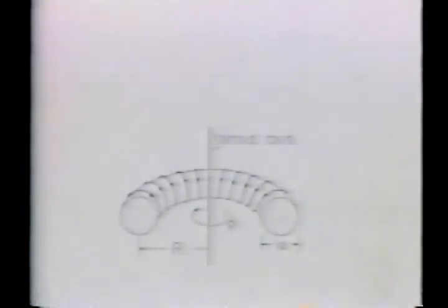A toroidal coil is tightly wound onto a donut-shaped magnetizable core. Each turn carries a current I. For the toroidal geometry, Ampere's integral law is enough to relate the current I to the H field in the magnetizable core material. Symmetry about the toroidal axis suggests that H is phi-directed.